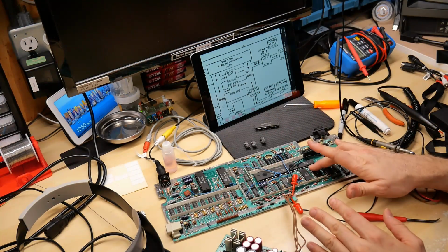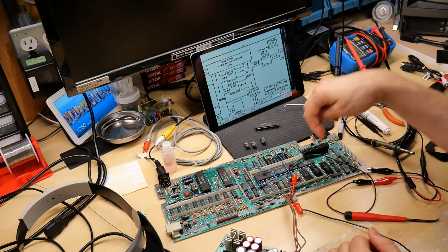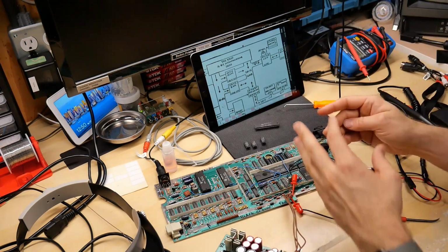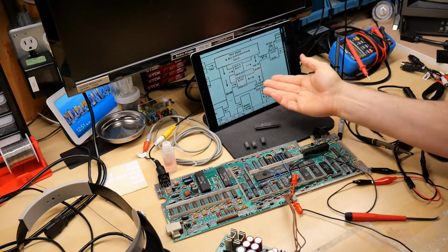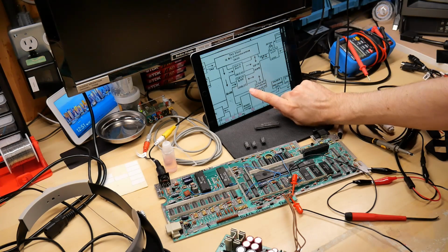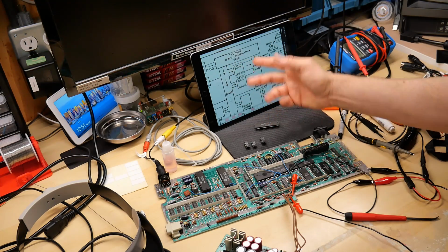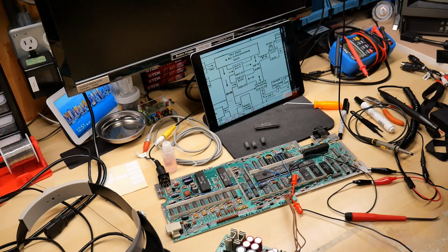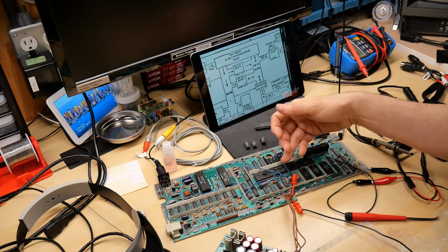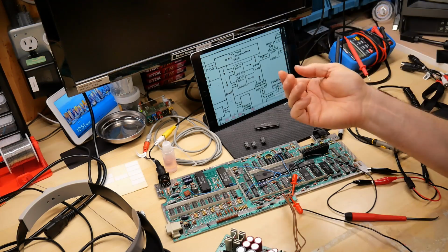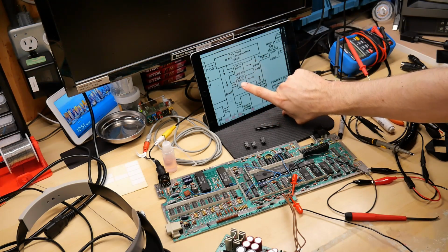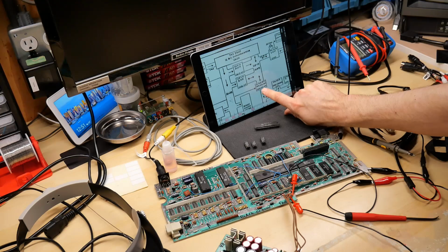The signals definitely look screwy, at least the data lines. And I'm not pointing out that it's definitely these RAM chips, but something is the matter on this board. So really at this point, it's a guessing game for me as to whether I should remove the RAM chips and socket them or remove these 3 bus converters and socket them. And I mean, I don't have another CPU. So if that's the problem, then there's no point for me to socket that thing. Not to mention, I think I do have a socket for this because the same socket has a 68,000, but I think the most likely candidate for a problem is going to be these RAM chips and maybe these transceiver chips. So let me go look at what these transceivers are, and if I have some of those in stock, maybe I'll pull those out as well and put sockets in.